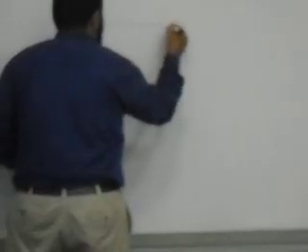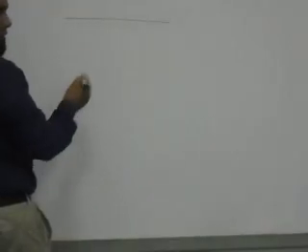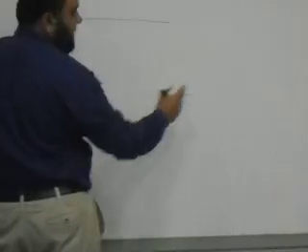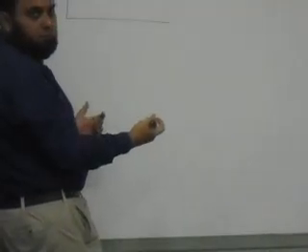Right. So if I go and look at my shear force diagram, I'll start with what? With this WL over 2 first. Do you agree? Fine. Then it will gradually decrease. If you take a section just before this support, and look there, you'll see what? You'll see WL over 2 minus WL. Right? WL over 2 coming up, and W times L coming down. Do you agree?